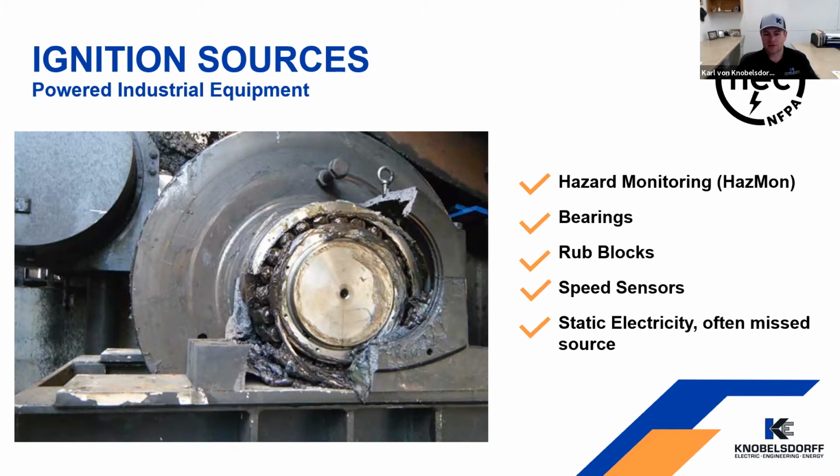So if you have not installed hazard monitoring in your facility, and if you have not tested that annually, that is something that you need to get on your list to do. Lots of systems get installed, but then they never actually get commissioned properly or get tested annually. So in any hazard monitoring system that you have installed, you should be testing annually to make sure that everything is working and functioning and will shut down in case of an event.